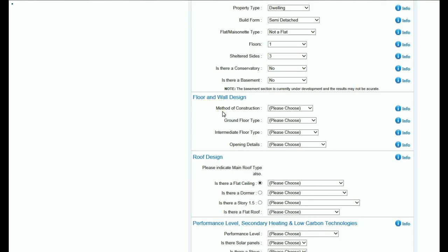This section of the calculator should be described as the construction method. Our design technology can be integrated with any approved or model details. It is our experience that each method needs a minimum of 50 typical details per method. These details need PSI values and need to be approved for structure, fire, moisture and acoustics. We have integrated our system with the Scottish accredited details and our own model details to the openings. The Scottish details have 3 methods of construction.